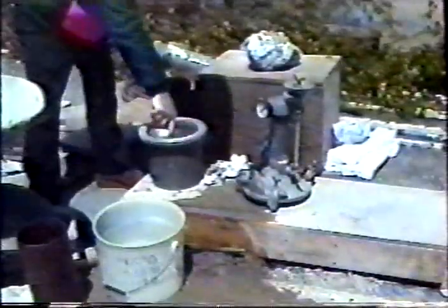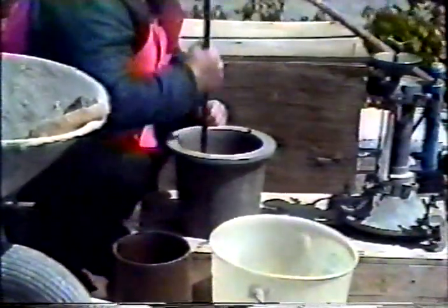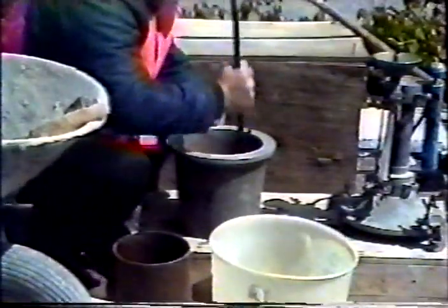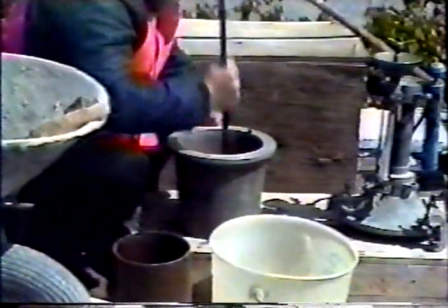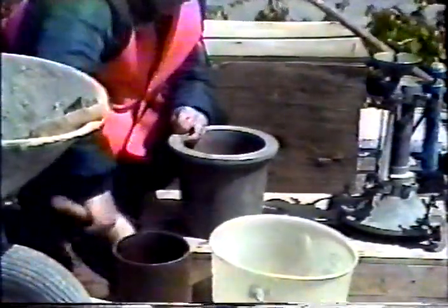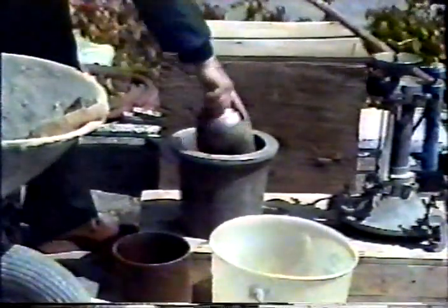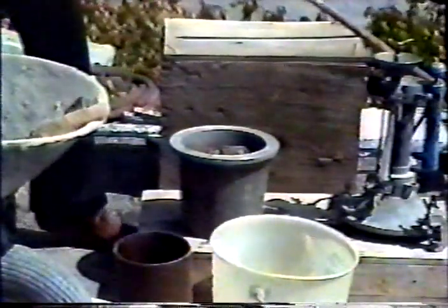When the tamping rod is used, the bowl is filled in 3 equal layers. Each layer is rodded 25 times, and the strokes are distributed evenly over the cross-section. The bottom layer should be rodded throughout its depth, but without forcibly striking the bottom of the bowl. After each layer is rodded, the sides of the bowl should be tapped sharply with the rubber mallet 10 to 15 times around the bowl's circumference.